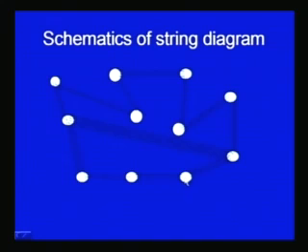So, after tying the thread around all the pins in such a way that all the stations have been covered, it will be possible to see the length of the thread which has been used in laying down the thread all around the pins, showing all the movements taken by the worker between the different stations in the course of production over a certain period of time, representing the representative movement of the worker between the different stations.